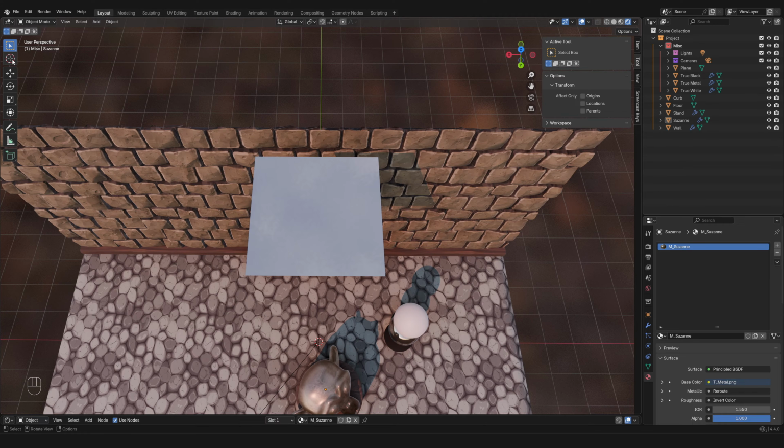If you click to the one below, you're now using the cursor tool, which with the left click allows you to move the 3D cursor that we reviewed in the previous video. And basically this is changing the behavior of the left click, because usually when this tool is not selected, if you want to move the 3D cursor, you have to press Shift and right click.